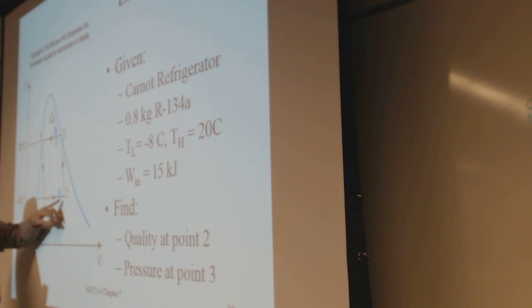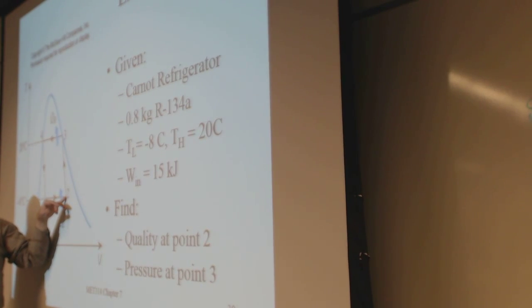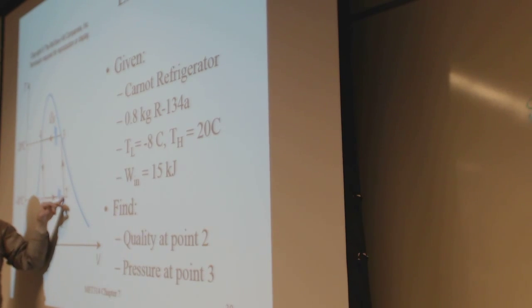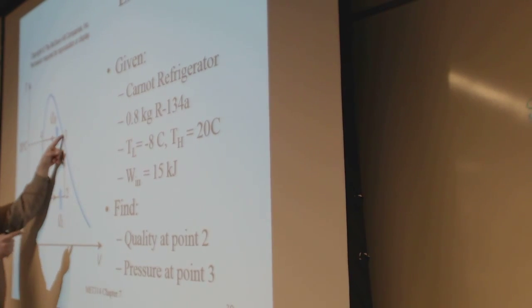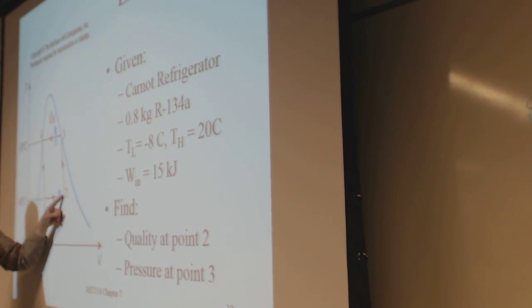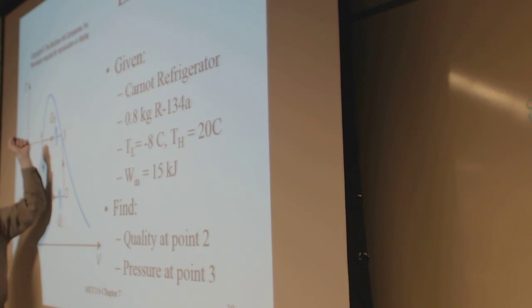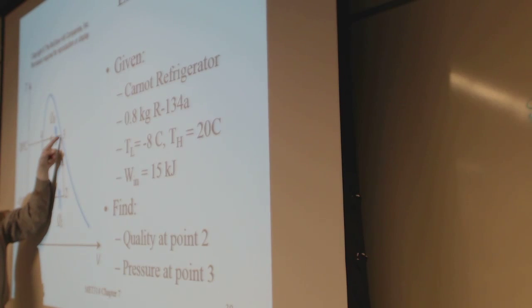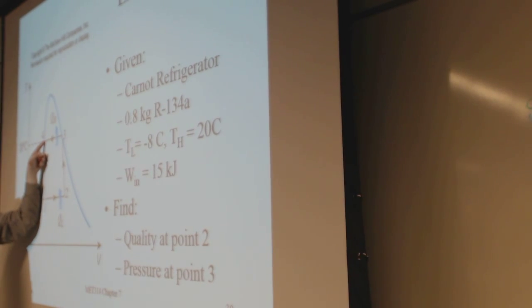If we then find at what point you can have that same value of entropy at this pressure, which is at saturation there, it's going to be between here and here. This process being isentropic, meaning the same entropy, this entropy value is in the table, so is that one.